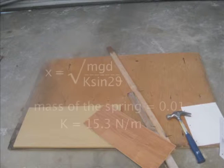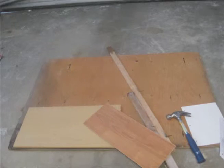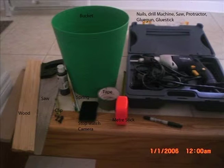X is equal to the root of mass multiplied by gravitational acceleration multiplied by distance, divided by the constant multiplied by sine 2 theta. The mass of the spring was 0.011 kg. The constant was calculated to be 15.3 newtons per meter. Using the x equation, the table was derived. The materials used are shown in the picture.